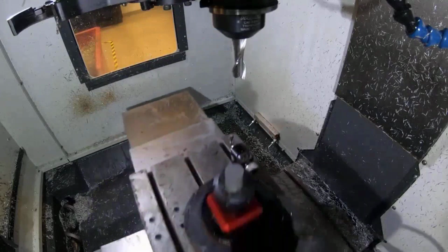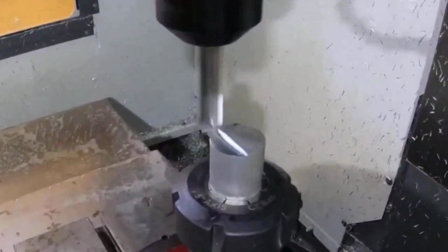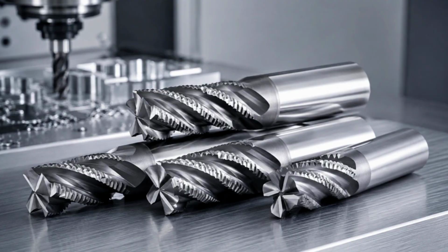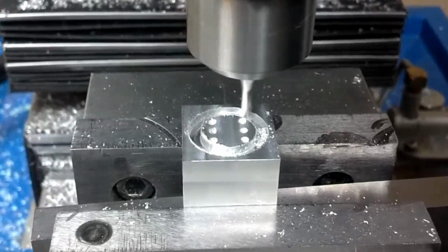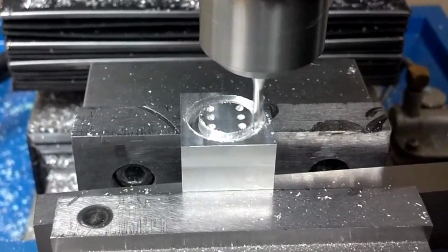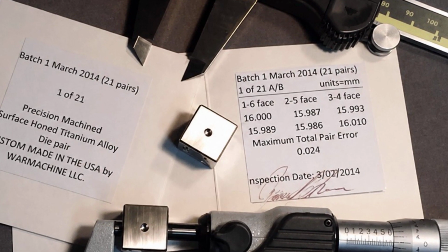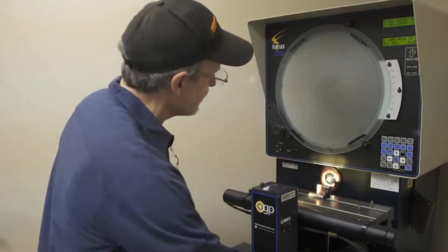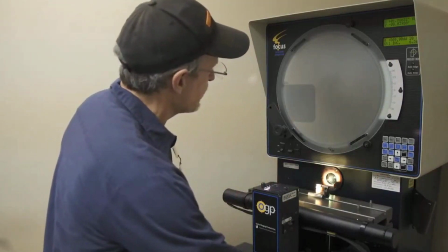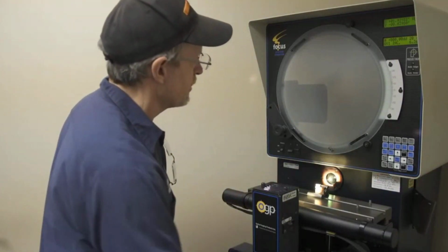During this roughing stage, high-speed carbide end mills carve away the outer bulk of the plastic. This step is aggressive, stripping away material to bring the blank within a few thousandths of an inch of its final size. But CNC roughing alone cannot deliver the final surface quality or eliminate microscopic geometric errors.